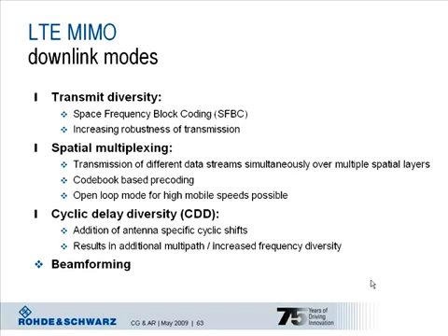That means the signal is pre-coded before transmission in an appropriate way, and this will be illustrated further in the following as well. There's an open loop mode and a closed loop mode available for this spatial multiplexing scheme. The closed loop mode relies on UE feedback, and the open loop mode is beneficial at high mobile speeds where the UE feedback may not be reliable anyway. So then the base station can operate in open loop mode.